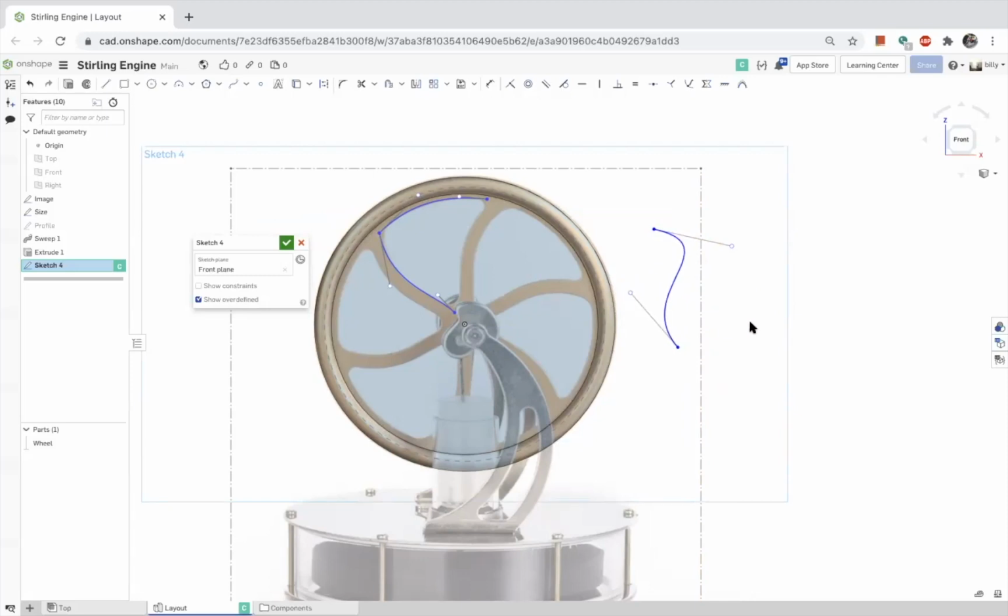So yeah, when you're looking at geometry on the screen, you need to look at the number of inflection points, and that's going to dictate what your spline is going to look like. Most of the time I'll break it down into single splines, and I control. What about an arc? I stay away from arcs, and watch what I'm going to do next, okay?